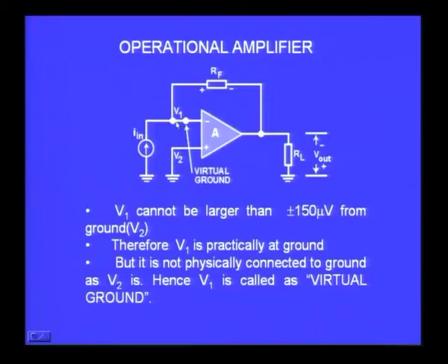This is close to ground potential because the other terminal is at ground potential. Therefore this becomes a virtual ground or virtual earth point. So if you realize that, much of the understanding of operational amplifier circuits becomes rather simple.